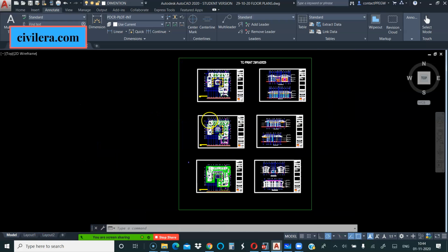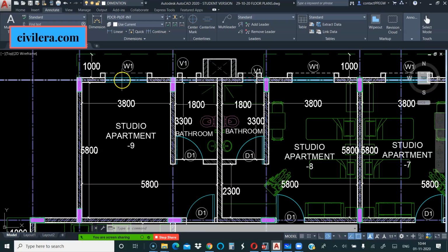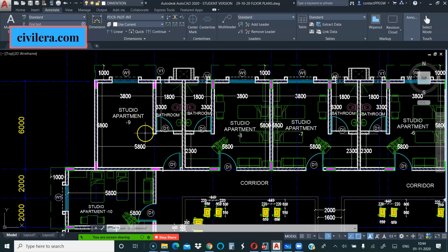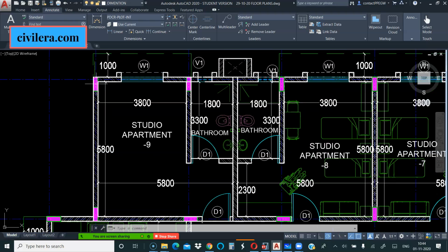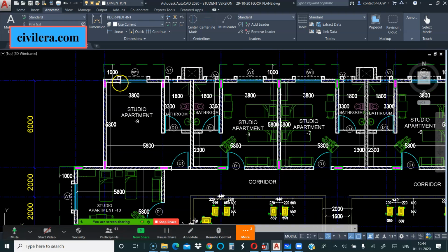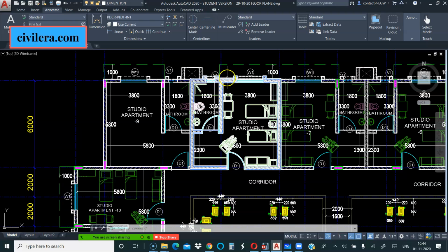Now basically our job starts now. Once we get the architectural plan, especially for beginners, see, architects might have indicated some column positions, but that necessarily need not be the final position. You have to look at your suitability, structural suitability. They might have indicated some columns.